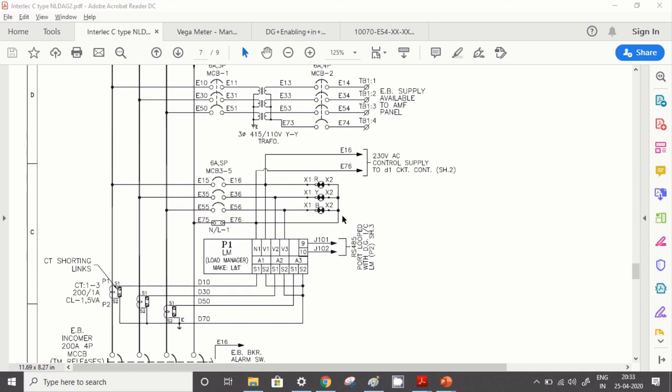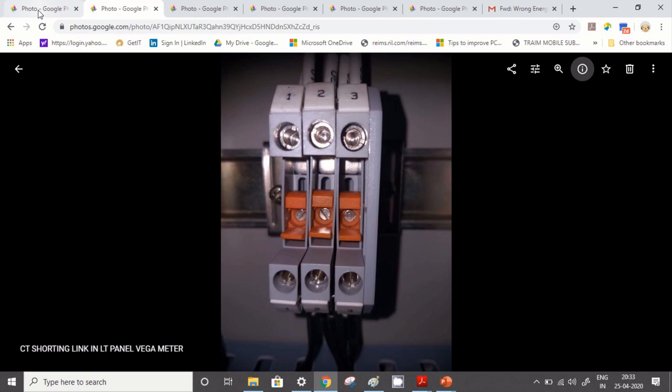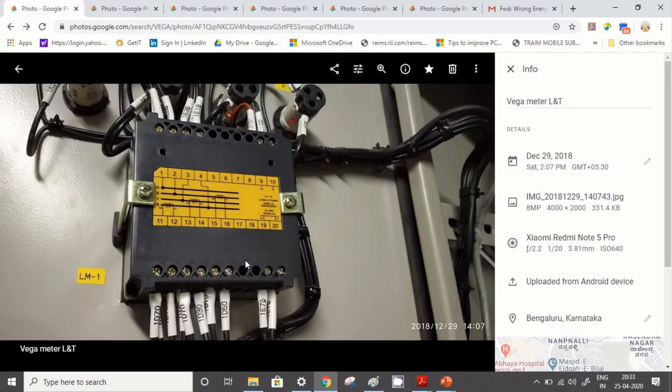Before we go to the next section, if you see here, this is 9 and 10. This is a very important parameter for the RS485 communication. I will take you to this picture again. You will see that 9 and 10 is your communication supply. Every meter has this 9 and 10. There is a grid meter, there is a 9 and 10, and from there